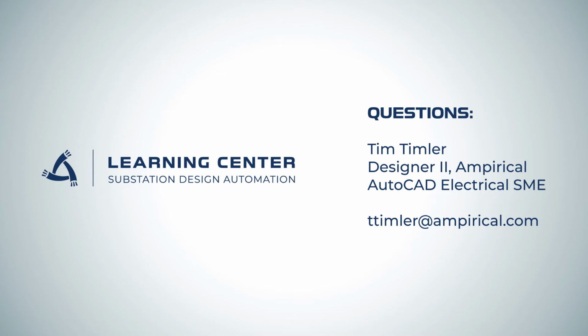I hope you were able to gain some insight into how you can successfully design using AutoCAD Electrical project files in a multi-user environment. The key thing to remember is that the AutoCAD Electrical Project Scratch database is built with the data written from the drawings in that project. This allows you to make drawing changes outside of the project file that can eventually be written to the main project file at a later time using AE Rebuild DB.